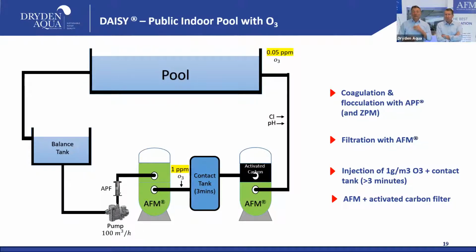My personal belief, or my learning, is that's too much. 20 would be okay. If you want to go on the very safe side, 30, but I would not go to 60. Again, same problem. You will lose all your ozone, and beyond this, you get a biofouling problem. The key one is that at the entry of the pool, your ozone level should be not more than 0.05 ppm.